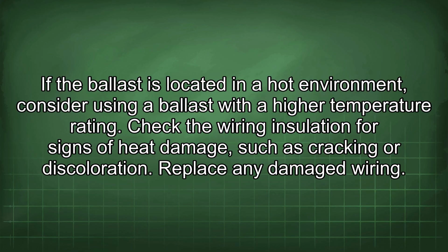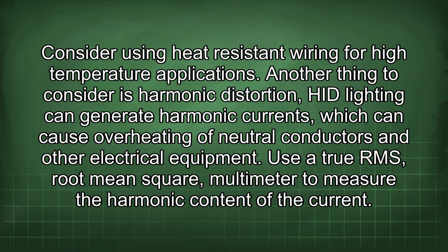Check the wiring insulation for signs of heat damage, such as cracking or discoloration. Replace any damaged wiring. Consider using heat-resistant wiring for high-temperature applications.